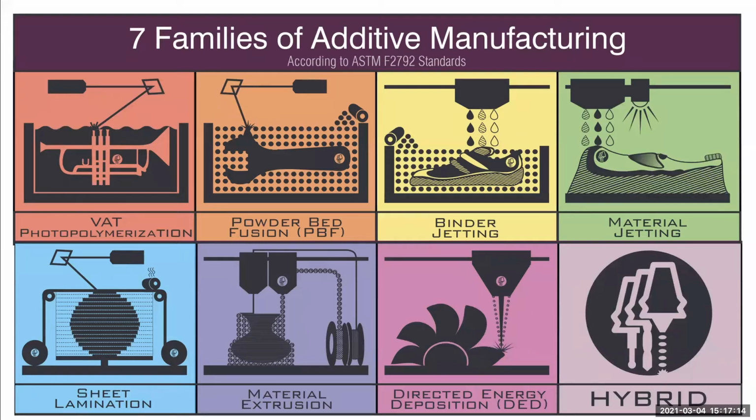And so you can have a little bit stronger of a part because it doesn't need to rest directly on the print bed, or it can have sort of more complex cavities in it that won't sort of collapse in on itself because it's just hot molten plastic resting on nothingness. You can sort of have a little bit more support, and then that support will just dissolve as you go through the rest of the finalization process. But we'll get into that. That's a little bit more advanced technique and stuff like that. But that purple one down at the bottom, material extrusion, that's the standard like consumer accessible 3D printing.